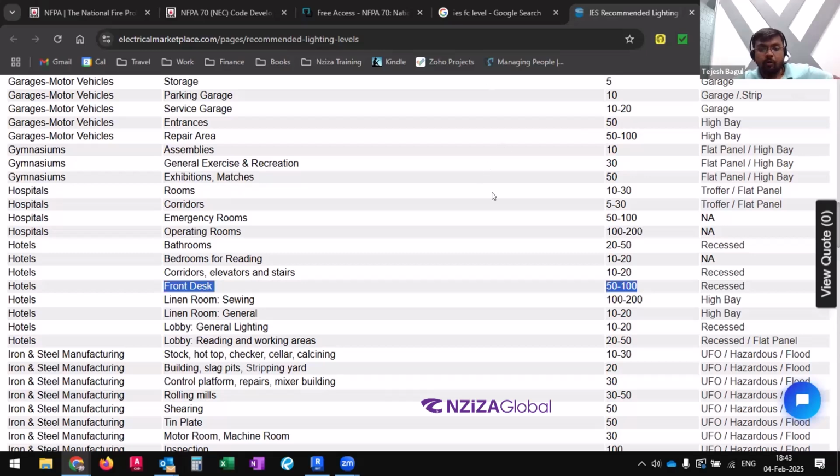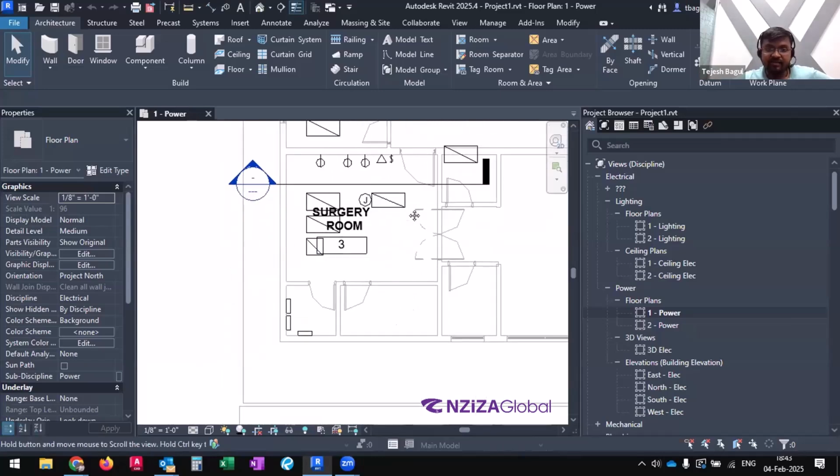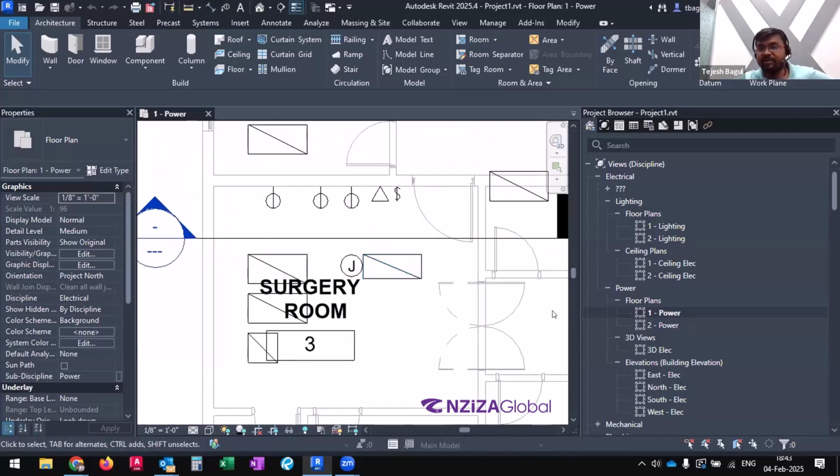All right, so now when we are talking about the formula, taking the lumen package in a given room, dividing that by the square footage of the room, and multiplying it with the efficiency factor, we get the foot candles. But dear friends, please note, last time when we did the exercise for the surgery room and we were trying to achieve somewhere around 80 foot candles, while the IES-NA recommends around 100 to 200 foot candles, what we had done was use 4 of the luminaire.